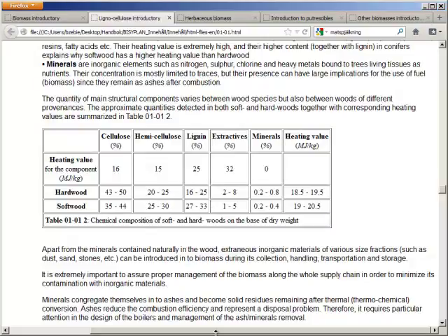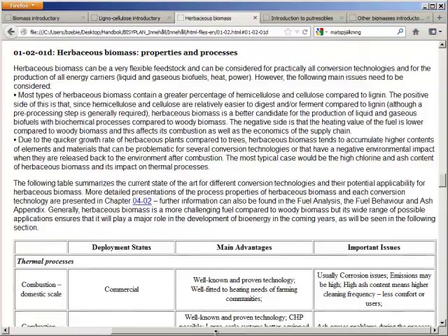As you remember, lignin is basically not digestible, and since the herbaceous biomasses will have a very much lower lignin content than woody biomasses, then herbaceous biomass can be used anyway as a part of the substrate, also in biochemical conversion processes such as fermentation or anaerobic digestion. The lignin will not be digested, will basically not be fermented, but since there will only be a minor amount of lignin present if the substrate is built up by herbaceous biomass, then the total process efficiency may anyway be sufficiently high to motivate the existence of an anaerobic digestion plant.